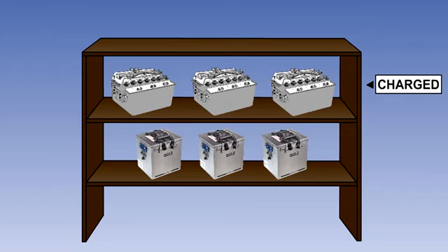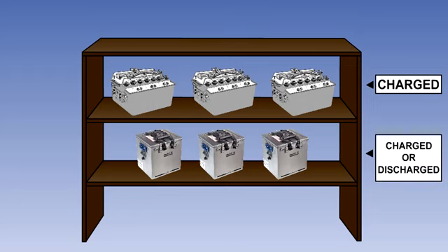Lead-acid batteries are stored in a charge state to prevent deterioration of their plates. NiCad batteries can be stored in a discharge state with no detrimental effect to the battery, and therefore have a longer storage life or shelf life.